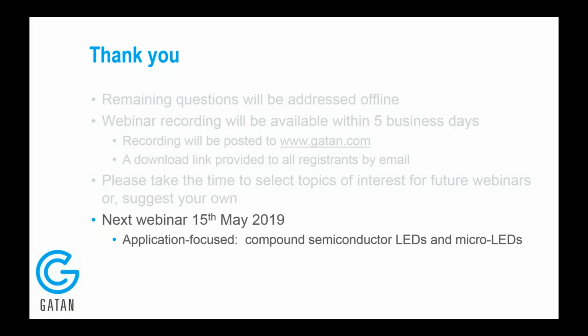So there are some particular use cases. For example, if you want to not only reveal the presence of extended defects within a semiconductor, but actually study their electronic structure based on their luminescence signature, then cooling the specimen down to nitrogen, in some cases, or helium temperatures, many of those defects then become luminescent themselves.